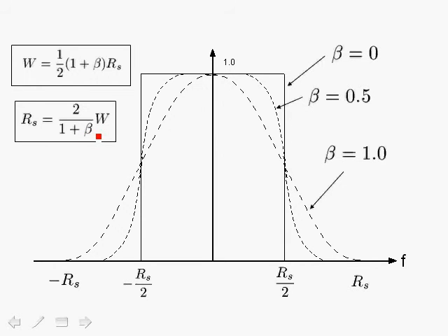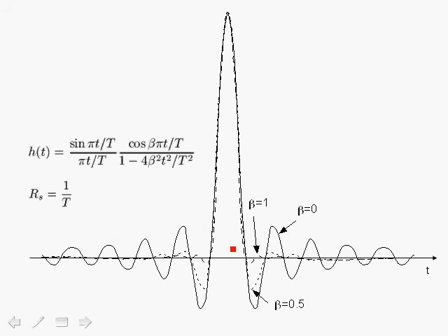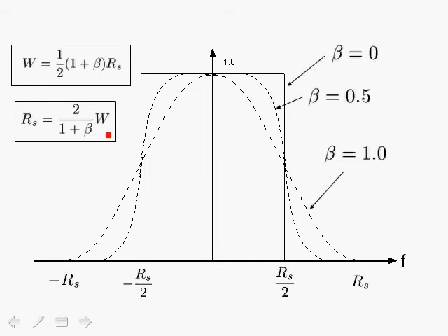The cost of that is, of course, more intersymbol interference. So for the case where beta equals a half, or we have 50% excess bandwidth, compared to the case where beta equals 1, we have more significant potential for intersymbol interference, but we get a higher throughput. In the extreme case where beta equals 0, the throughput is actually twice the bandwidth. The symbol rate is twice the bandwidth.